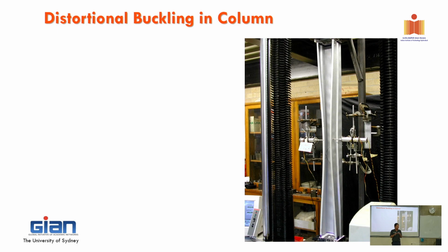So normally they restrained the member somehow to stop the flange going in and out, to force just local buckling or the other mode, right? So they tried not to understand, not to accept this one. Until Professor Hancock tested some sections like that one, and he didn't restrain them, to make sure that the flange could move in and out. And then he found that mode in here. Okay, so that's the first one.